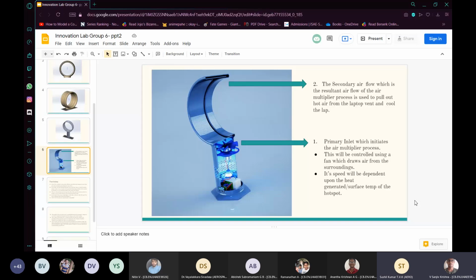See, your heat transfer is through convection, and that depends on the air velocity. You are reducing the air velocity by this process. How do you say it's a better way of cooling the laptop? I am not getting it. I am confused.